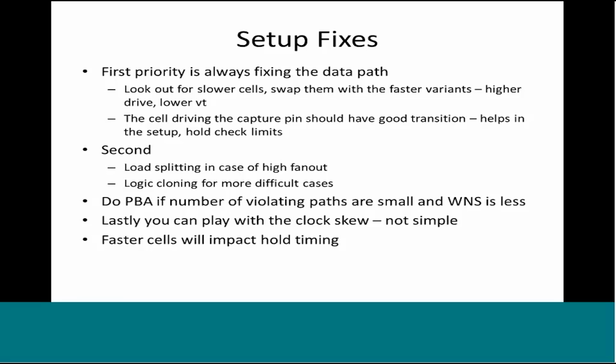Your total delay would improve. Yes, you are adding a new buffer, but the combined delay of this buffer network should be less than the case where a single buffer is driving 20 fan out. So this is a more advanced case, the load splitting.